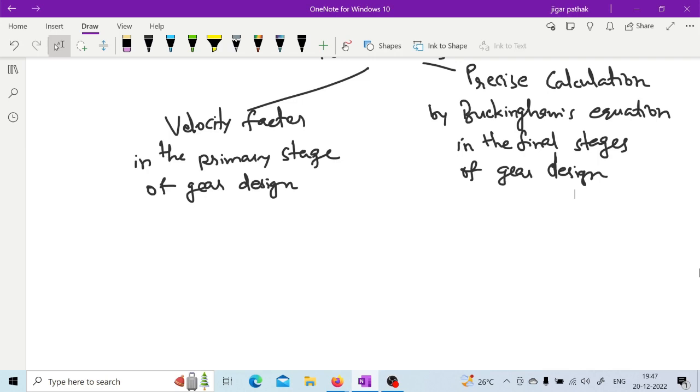Is it due to the contact time between the gears? No, it is not related to time. It is basically that whatever torque or tangential force is being transmitted is not the same throughout the operation time. It may vary, at the driver end or at the driven end, and in what amount it varies. All these things need to be considered while deciding the service factor. Every time it is not simply a constant torque and constant speed being transmitted from one gear to the other.